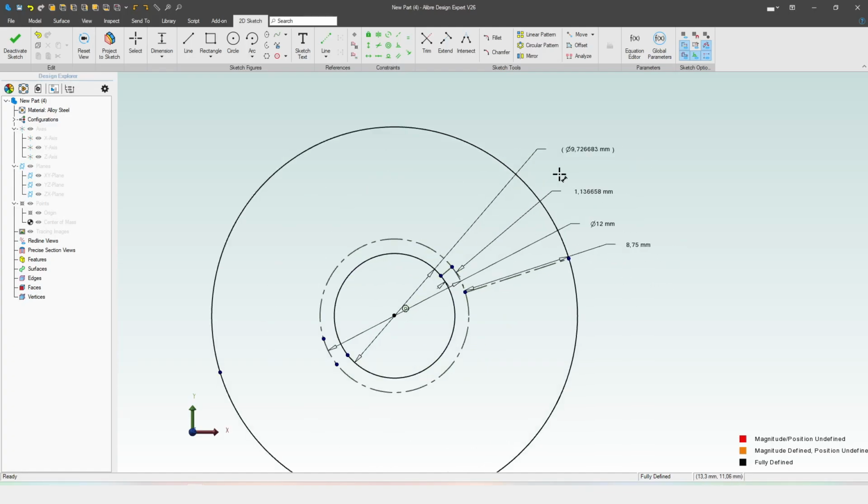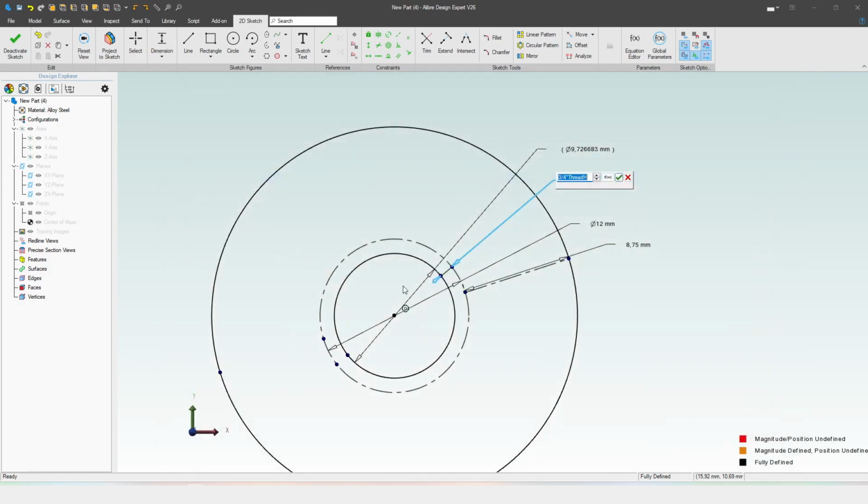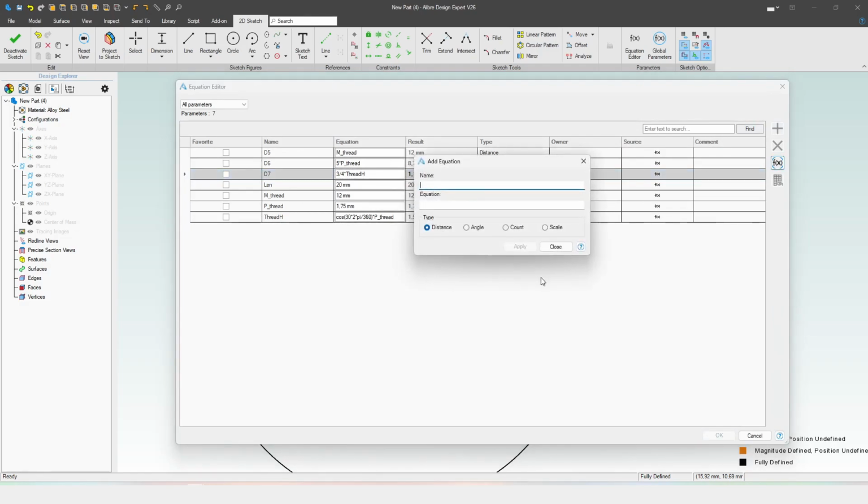Okay. And if you wanna know where you're standing, we can have a driven dimension showing you what is this minimum minor diameter, right? This is what you're going to get. Now, if you want to make this larger or smaller, here's where you're going to be doing it, right? And if we open the equation editor, we can add a tolerance. Just going to call it tall, and you give it a value 0.01, right? So this is something. I hit escape and it didn't. Yeah, I do that all the time, guys, all the time.